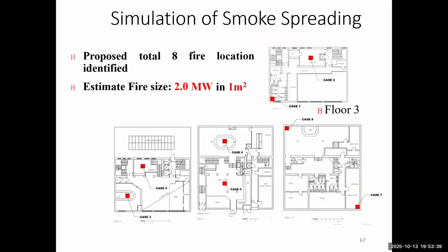And in our fire dynamic simulation, we should not just simulate one fire. We should simulate multiple fire scenarios in different locations and with different heat release rates to find the worst case. And here we can see we have the 8 potential fire locations.